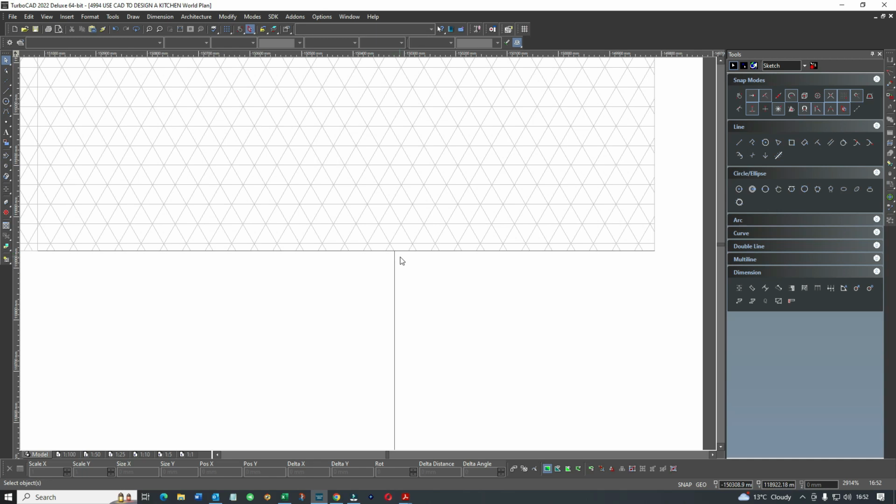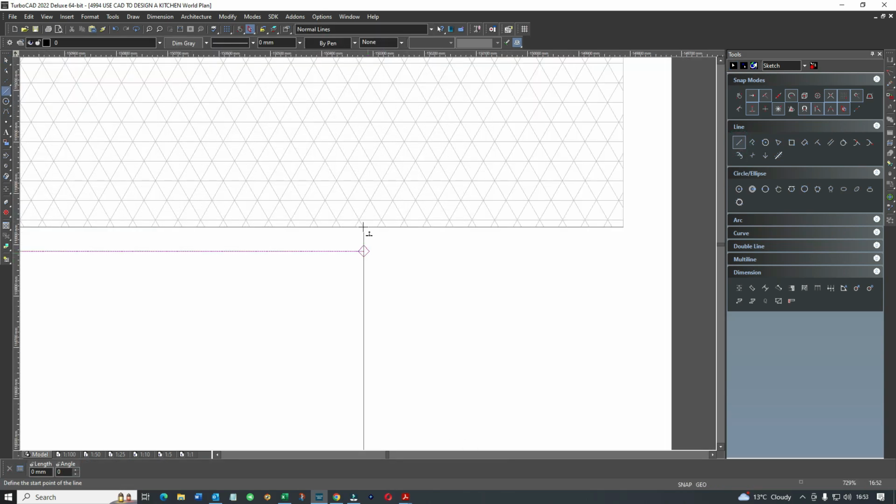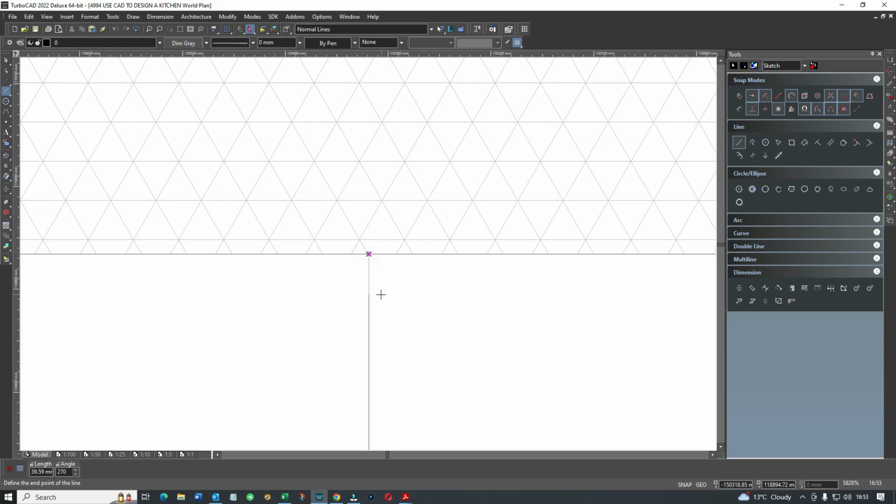again, you know, the principle of the doors and the drawers hitting the drawer handles there. Can't do that, so we're going to come in 30 mil again. Sometimes we do more, depending on what the handles are. If the client picks a big deep handle, then we have to allow more space here in the corners. So again, we're going on a 30.